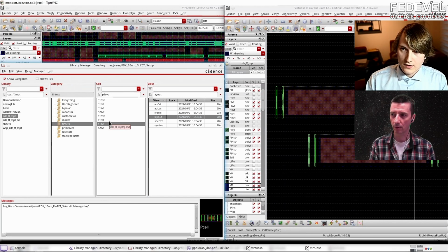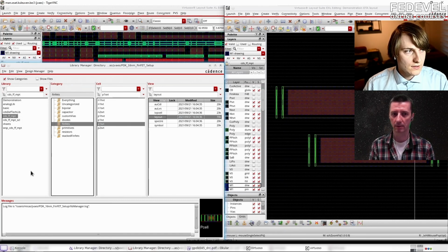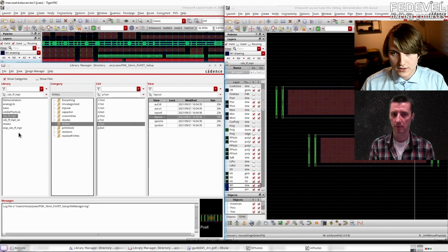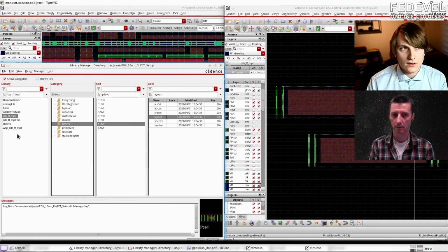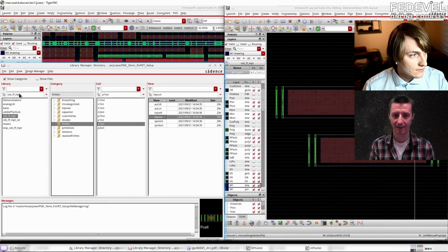Okay, and then if you change the parameters, do you need to simulate it then? Because how do you know what happened with the transistor when you change some parameters? Indeed, we have to simulate all of this, and that is also what they include. Usually it's using BSIM, which is this very complicated model. I think it's more than 200 parameters for a single transistor.